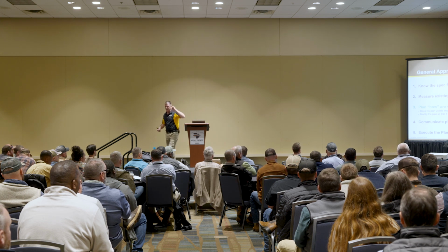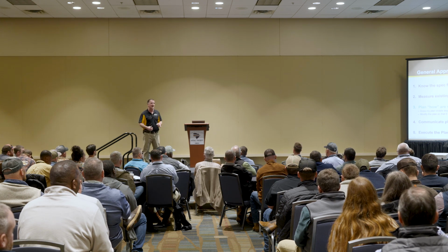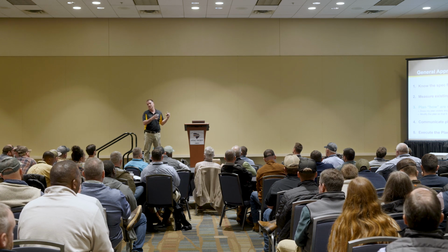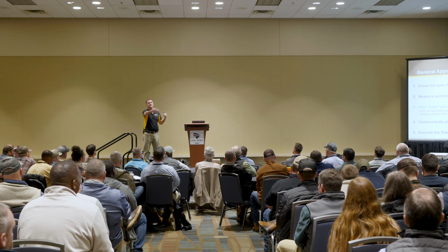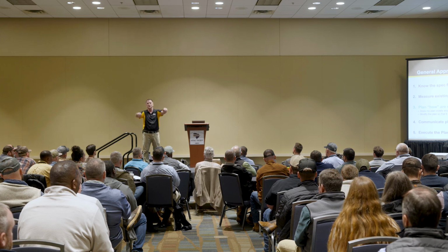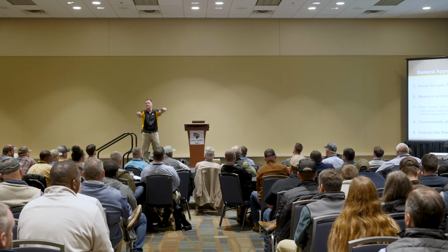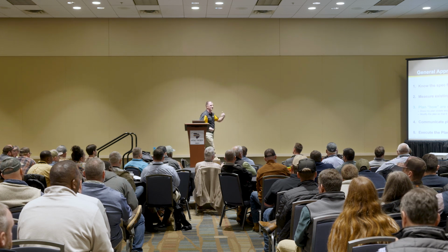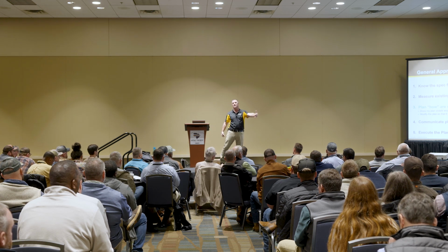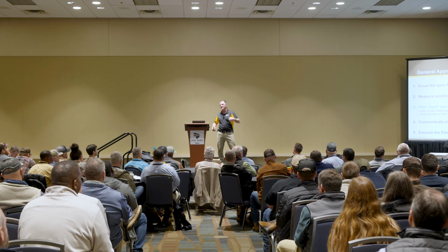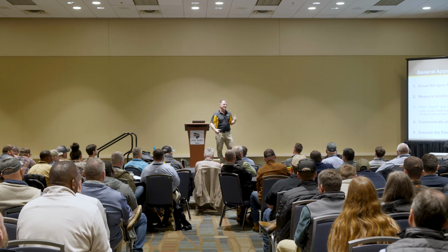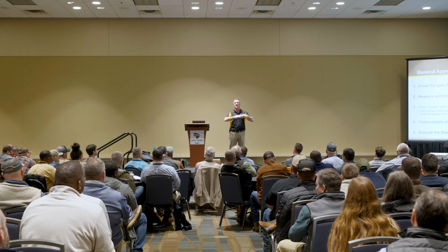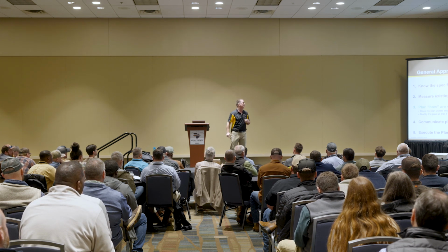I put my days-as-a-contractor hat on when I was with the paving crews, and we were not always the best, to be honest, at getting ahead of paving and checking the existing slope before we got to it. That's something that really pays dividends, getting ahead of that, knowing what you have coming up. It's going to save a lot of headache, a lot of headbutting, when you've got 5, 10 trucks lined up and now you're trying to figure out how we're going to pave this and keep the right thickness and all that.